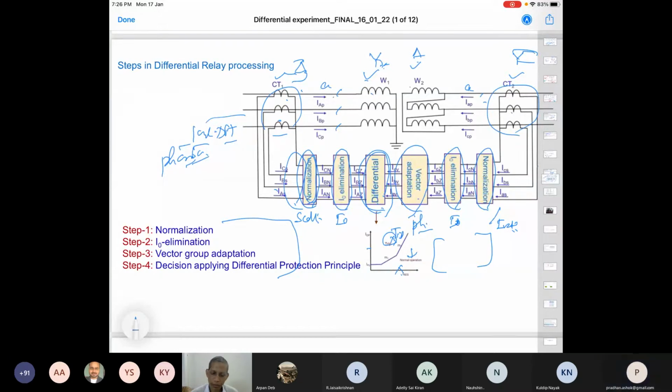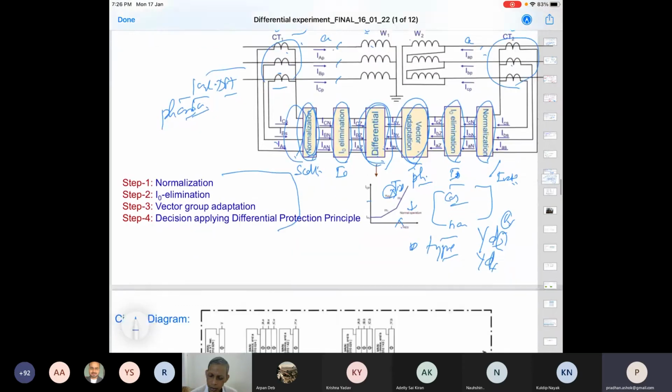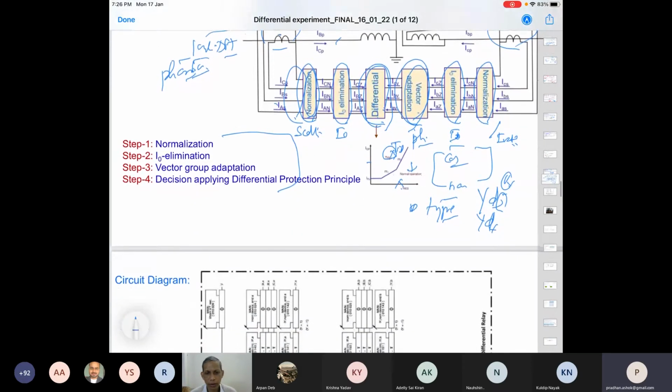This is nothing but a matrix multiplication in terms of the cos. You can see that term and so 30 degree k factor k. Depending upon the type of transformer, whether it is YD5, YD1, this k is some constant. Accordingly, a very generic matrix is used, and you multiply it here to compute the phase in terms of that. So this is what the relay does. You only have to enter what type of transformer it is.